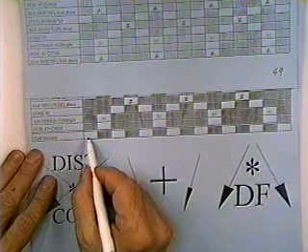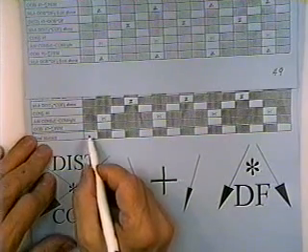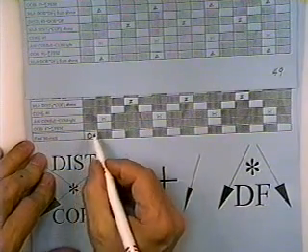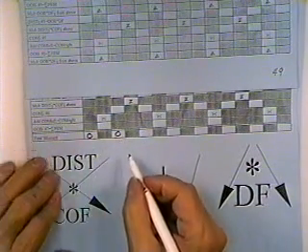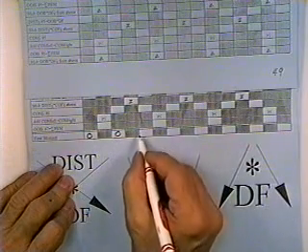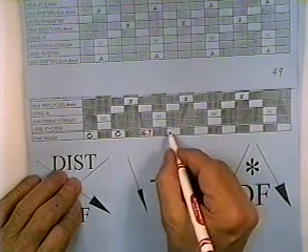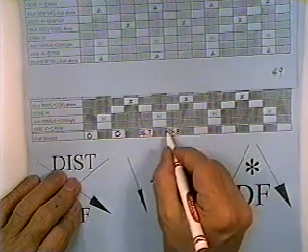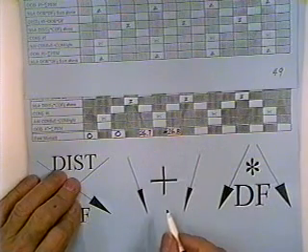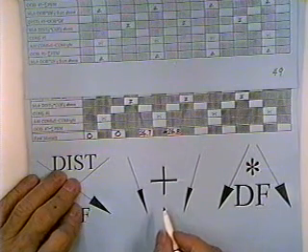The final moment on the last page, a lot of times you don't use all 2 or 3 pages, because the numbers close out pretty quickly. 0 for the final moment. Well, that's on each side of a pin, so that makes a lot of sense. There shouldn't be any moment in the pin. You get a 26.7 in this member, and 26.8 minus on this side. See, that's on either side of joint A. Were it a perfect world, those two numbers would be the same number.